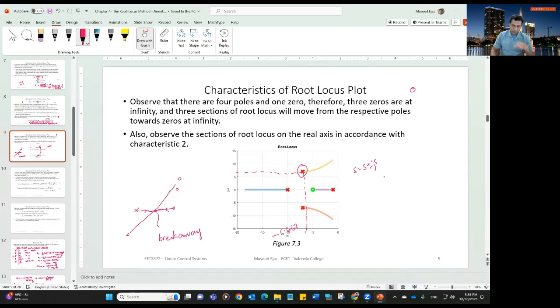So understand that when we say plotting the poles or plotting the zeros, that's what we mean. It's very easy to do. If the roots are in front of you, with your hand you can always put a circle for zero and a cross for pole. But when you're doing it through programming, you have to separate the real part and the imaginary part, and then plot the real versus imaginary on the S-plane.